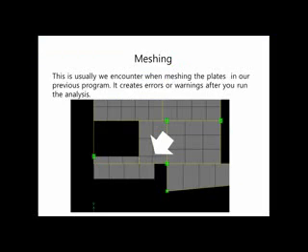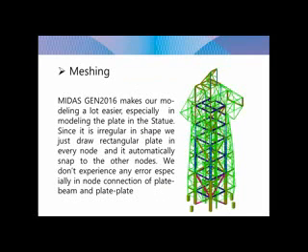Under the node element tab, select the auto mesh icon. For this case, the method used was node. The mesh will be automatically generated by selecting the node's bound area. A quad triangular type is suggested for irregular meshing areas. This is the structure after putting all the plates around the frame. All the nodes snap to each other easily.